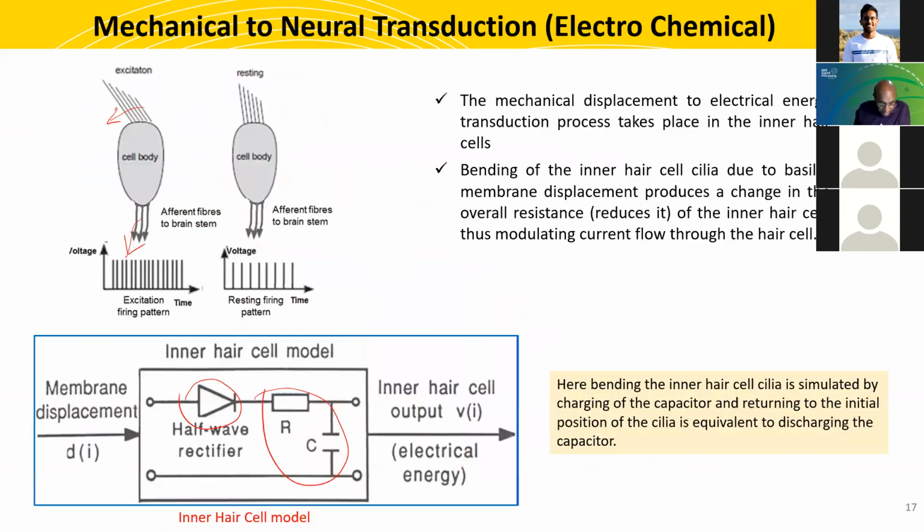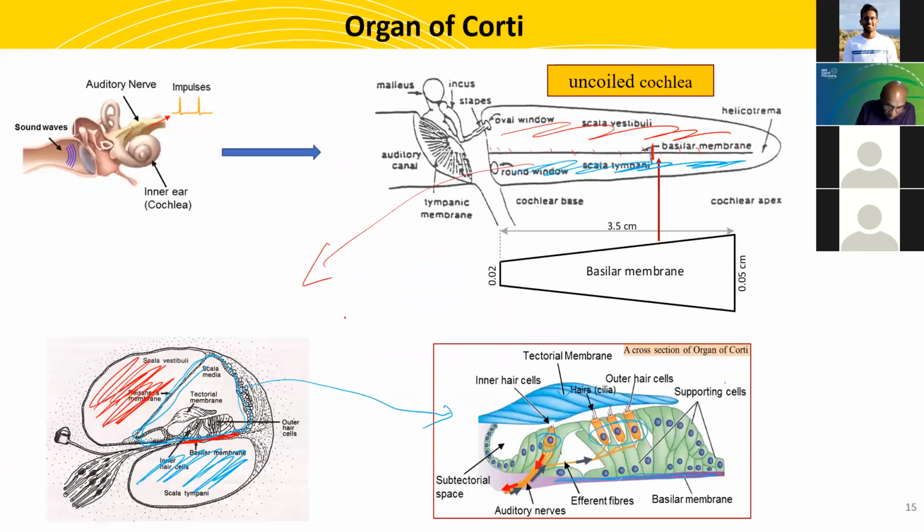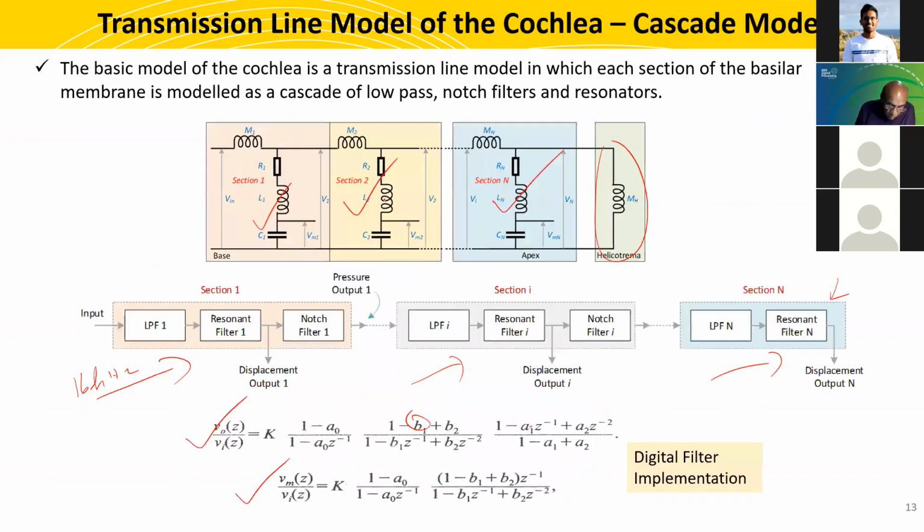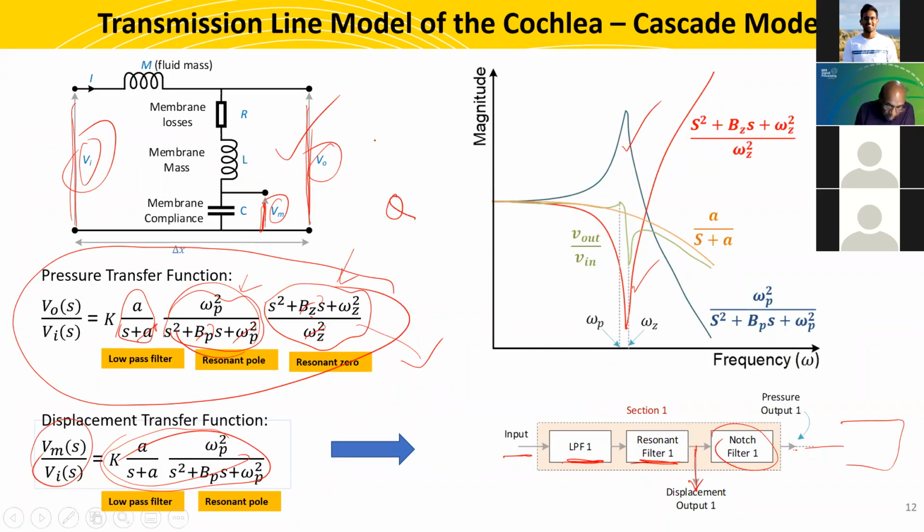So you see, this is the fundamental equation. So we have the Q value. If you know the Q, I said it varies from, let's say, 2.5 for low frequency to 40 for high frequency. So the bandwidth is equal to the center frequency F divided by the Q. So once you select this one, we have the bandwidth as well.